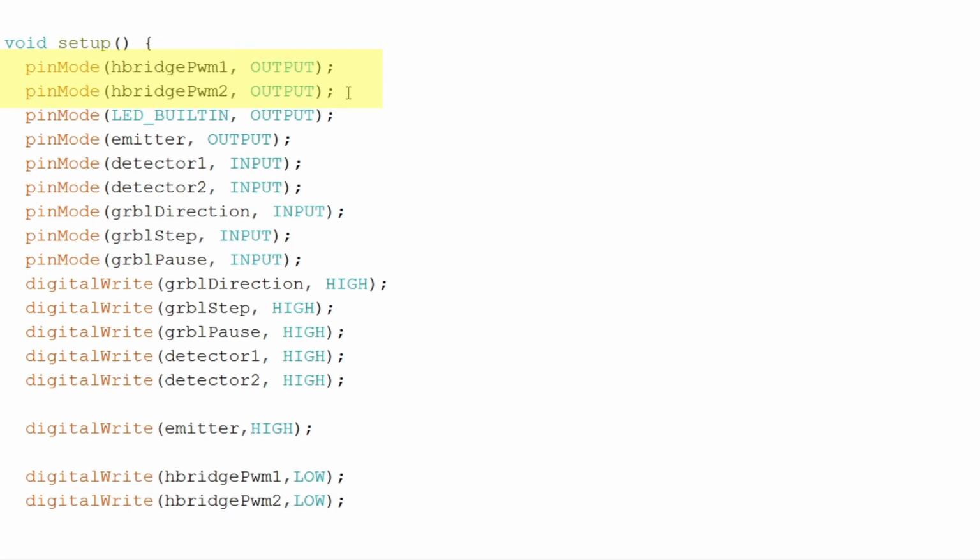the H-bridge. An H-bridge also has an enable pin that can be used by a microcontroller to enable or disable the H-bridge. I hardwired the enable pins on my H-bridges to keep the program as simple as possible. Next, the pin for the built-in LED is set as output. The LED is used to indicate the encoder state and indicate tracking problems.